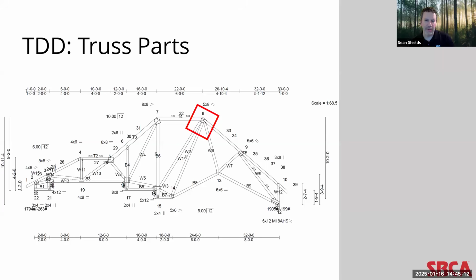Quickly, maybe another example is if a manufacturer may limit the number of different sizes of connector plates that they keep in stock at any given time. Some component manufacturers have a majority of their book of business based on a certain type of construction, whether it's small single family or large agricultural. And because a majority of the product they put out uses the same size plates within a certain spectrum, they may not keep in stock some unusually sized plates.